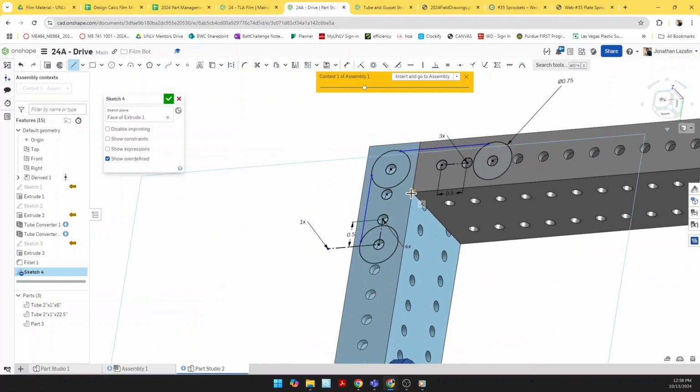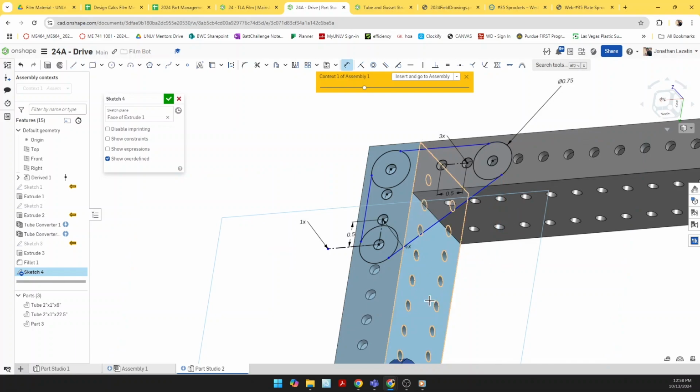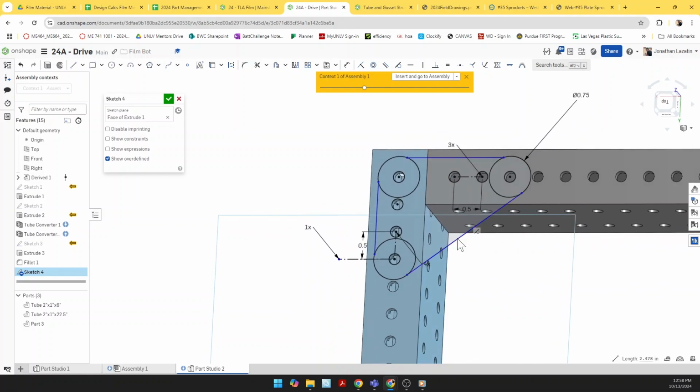And what I don't want to happen is I don't want this gusset to cross over this corner to eat up some of that space. Just in case if I did a line like this, just in case this intake tube needed to go forward a little bit more, this gusset, if it was designed like a triangle like that, might get in the way.